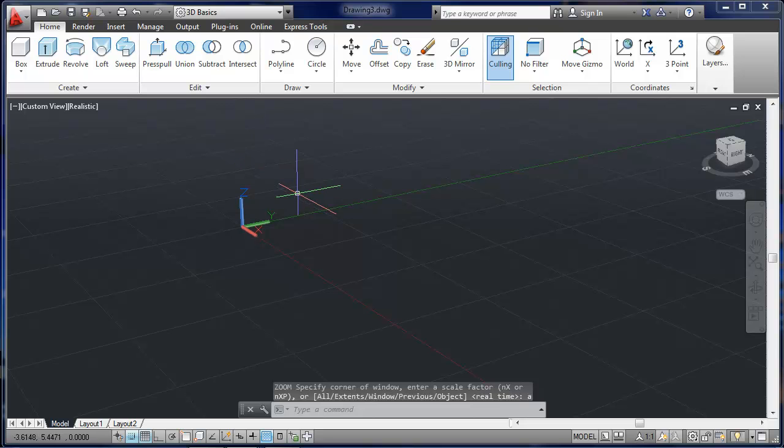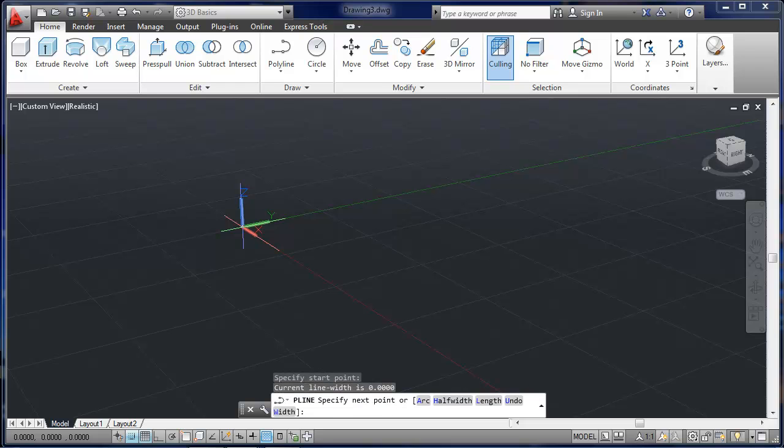And then I'll begin my 2D profile sketch using the polyline command, starting from the origin of 0, 0, 0. And you can see that in the coordinate display in the bottom left corner of the screen, right below the Model Tabs and Drawing area: 0, 0, 0. My first line will come out a distance of 4 in the x-axis. The coordinate display should now read 4, 0, 0, and it does.